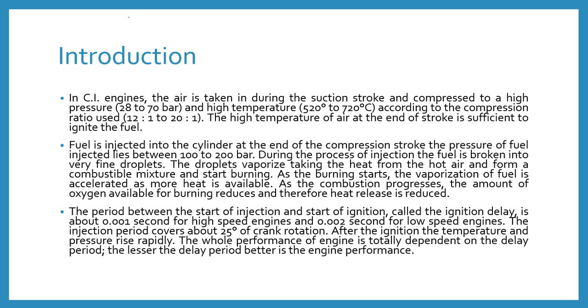During the process of injection, the fuel is broken into very fine droplets. The droplets vaporize, taking heat from the hot air, and form a combustible mixture and start the burning. As the burning starts, the vaporization of the fuel is accelerated as more heat is available.